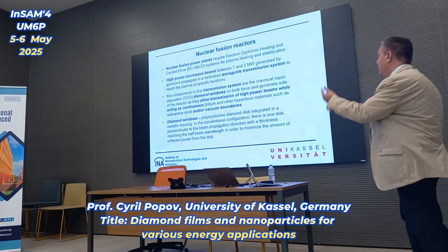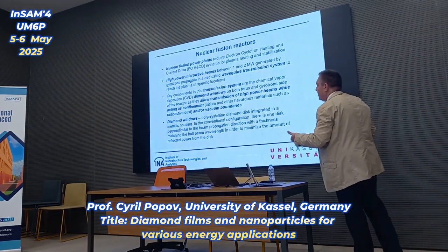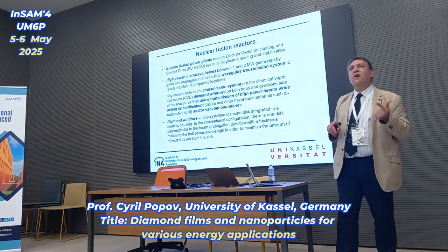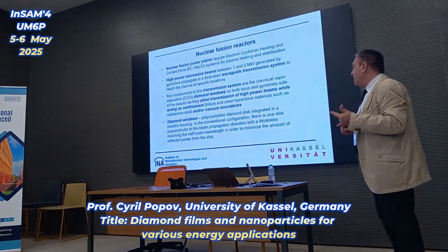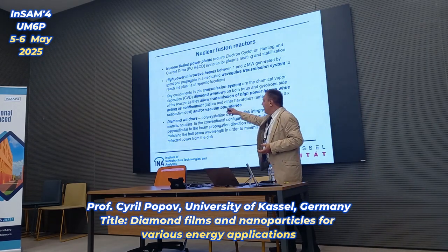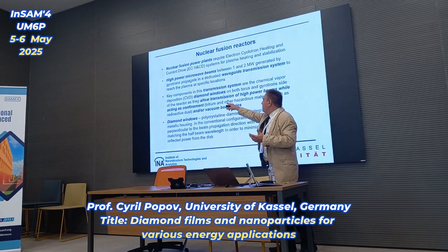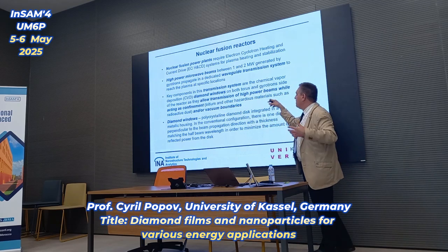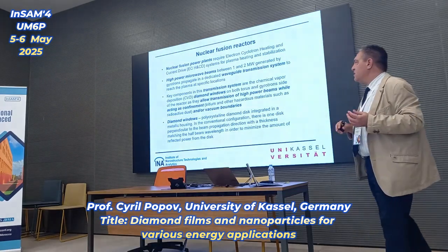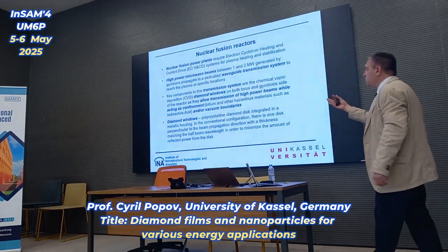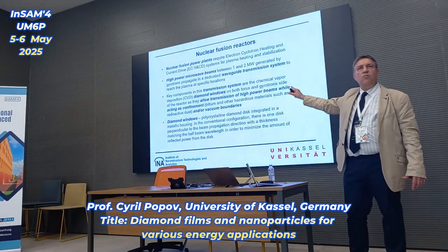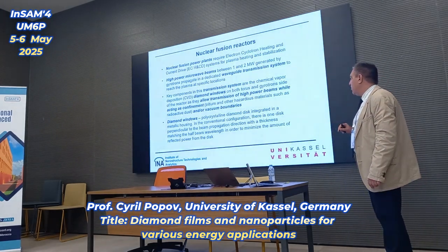because diamond is the only material that fulfills all requirements. First, it has to be highly transparent. Second, it should have high thermal conductivity. Third, it should confine the vacuum conditions, but also isolate hazardous materials. Also, there is some radioactive dust from the rest of the systems. And such windows are made of polycrystalline diamond, in a similar way to the films demonstrated.